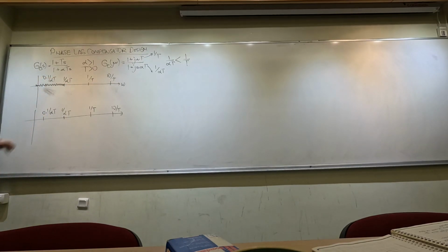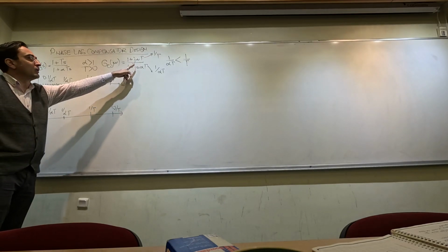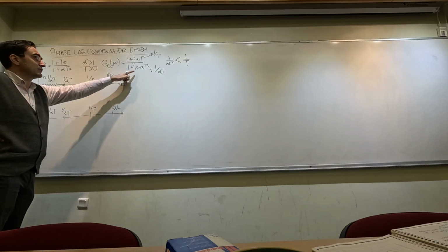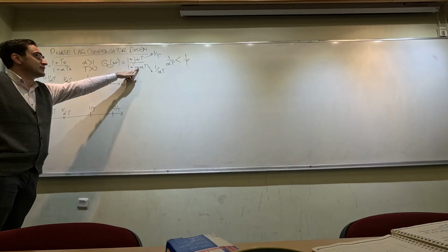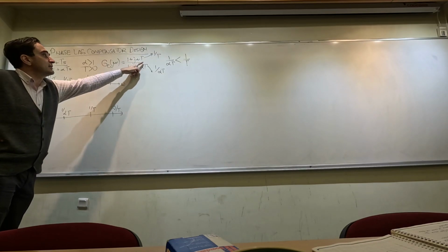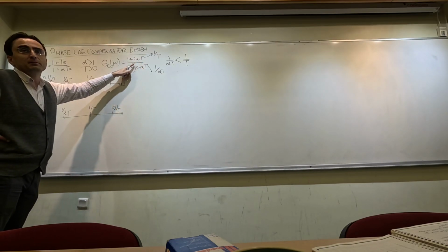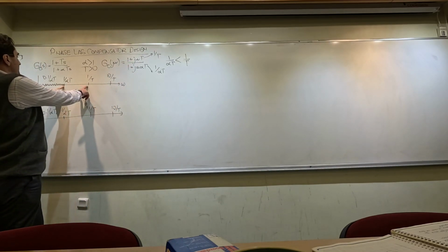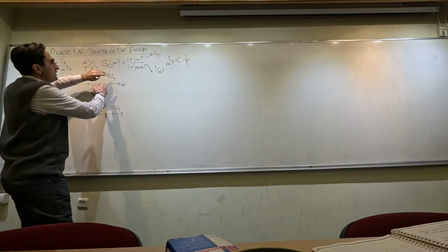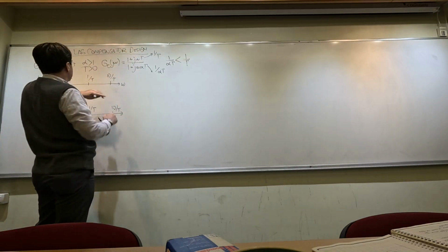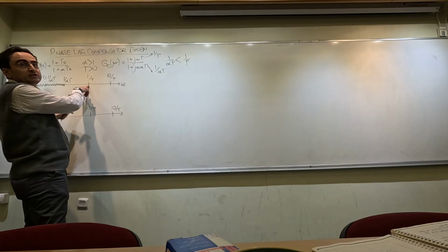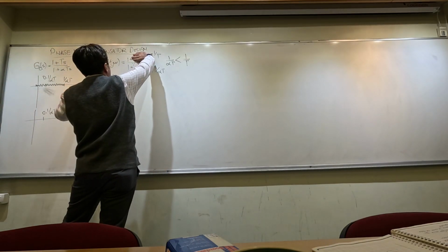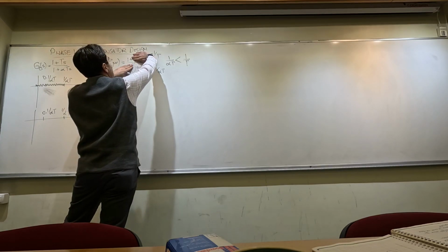Afterwards, we are going to hit the corner frequency of the denominator, which starts to become important. When the frequency is between these corner frequencies, the numerator is still 1, because we have not reached its corner frequency. So the numerator is 1 in this interval, and the denominator is looking like this.